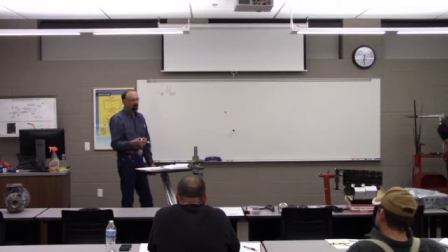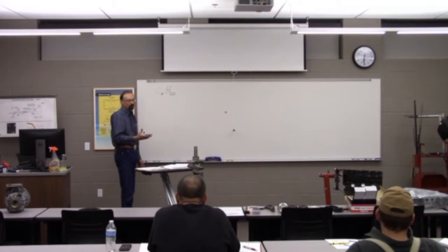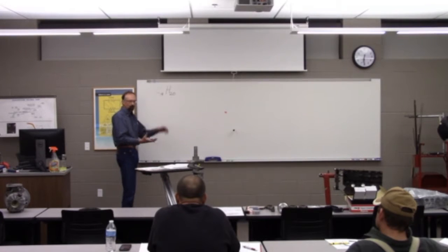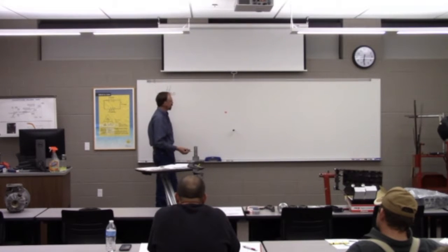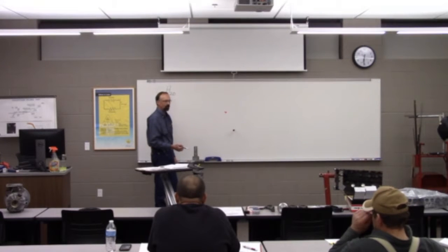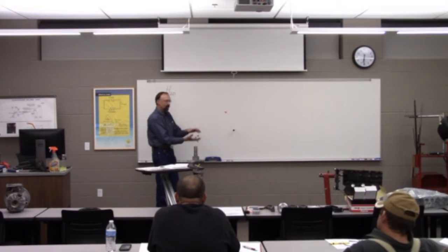But they all have different characteristics too. And so depending on which fuel we're using, different compression ratios work better as far as that compression stroke where we're compressing all the air and fuel. So even within gasoline, different types of gasoline require different compression ratios to run really well. So wanted to talk about compression ratio.